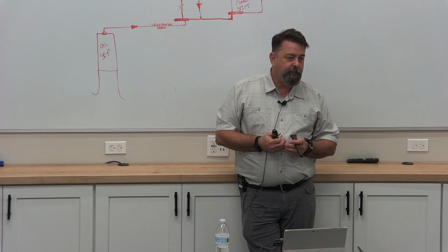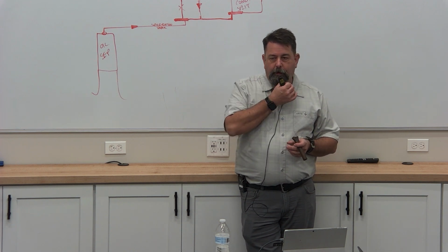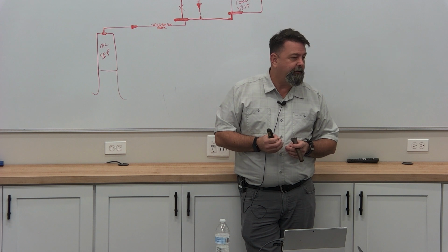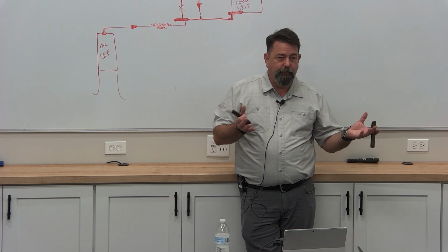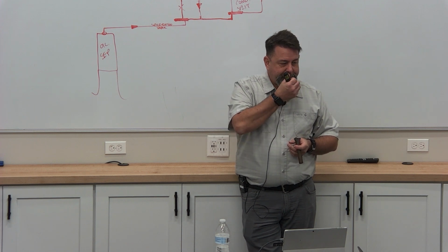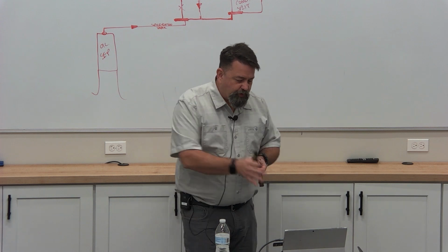So the coil's clean. Is it wet? Yeah, it's probably gonna be wet. Okay, but it's gonna be at 55% at 75 degrees, right? Which, by the way, is 54 degrees dew point, right? Okay. So just know that.